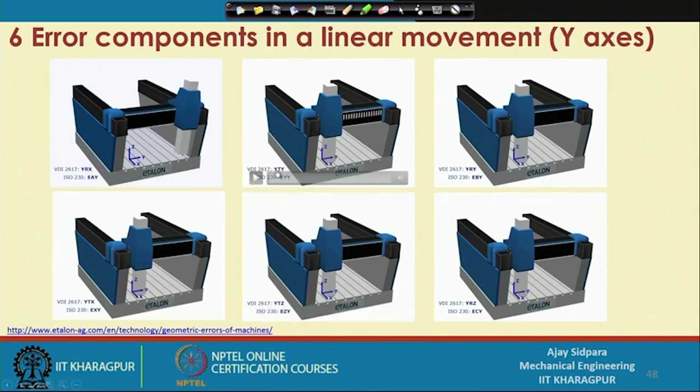So, here it is in tilt motion in the y direction. So, now it is, sorry, it is tilt motion. Now, you can see again this white color and the red color. What we need, that for uniform motion we need this spacing same for all the things, but if you see this red color, then spacing is somewhere like this, that it is accumulated at one location, then there is an off position and again there is a bunching of some more. So, you are not getting a uniform motion and because of that you end up with more amount of forces and at the end your tool may be broken.